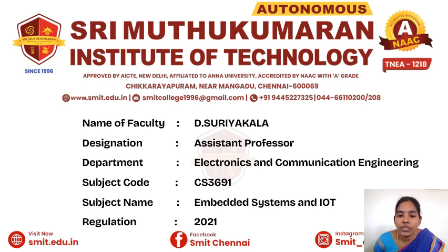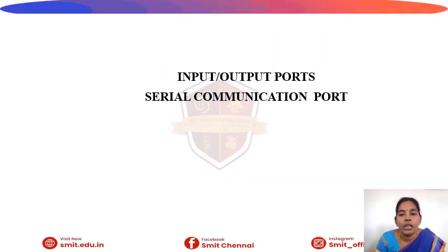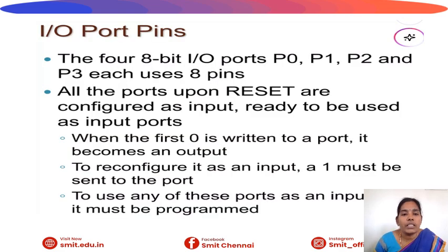In this video, we are going to see about the topic embedded systems and IoT. In this unit 1, you can see the topics about input-output ports and the serial communication ports. What are I/O ports? I/O ports are used for giving inputs and getting outputs in the 8051 microcontroller. There are 4 I/O ports in the 8051 microcontroller: port 0, port 1, port 2 and port 3. These ports use 8 pins as 8-bit ports.